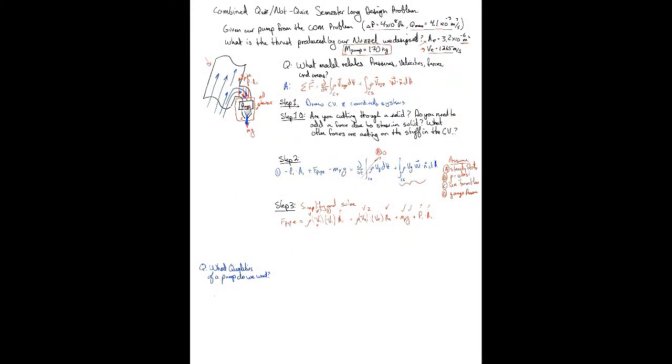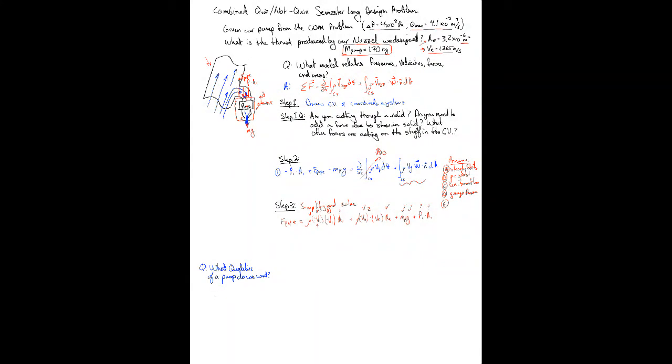So we're going to make a few assumptions here. Let's do this, right? We're going to assume that by design, remember I talked about this, we want the velocities and pressures to be low in our main pipe. So by design, V1 is much, much smaller than V2. Because the whole point of the pump is to add a tremendous amount of kinetic energy to this fluid to produce our thrust. So we can say that this is approximately equal to 0, especially compared to this component here,